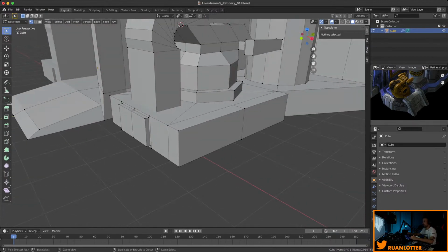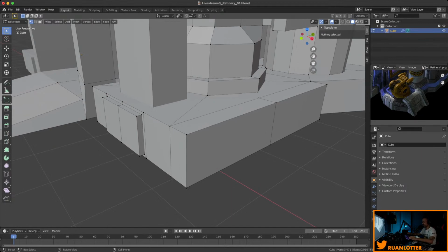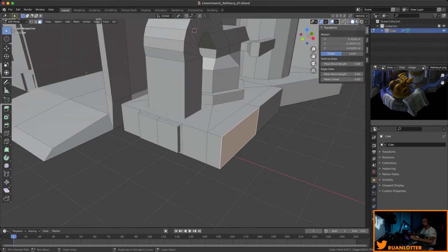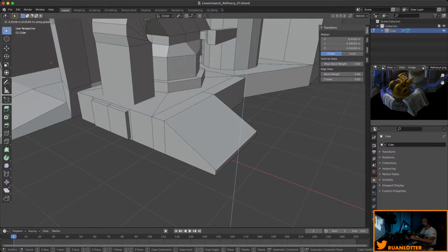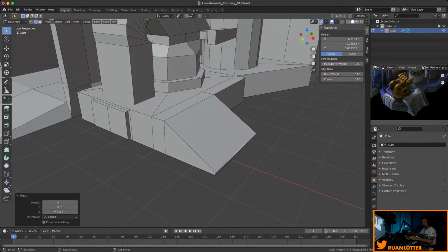Okay, for this one, I don't think I had to do this loop cut actually, because I can maybe just do a normal extrusion to the side and then push this down like there, and then we can do the sides maybe with 2 loop cuts. So let's place this one on this side and make it about 0.6.